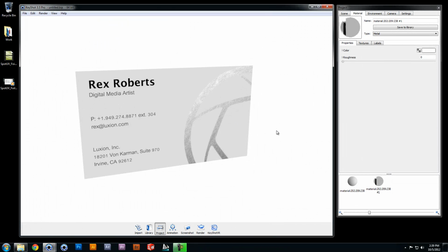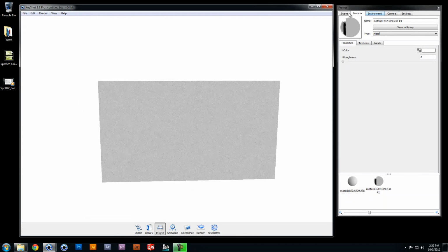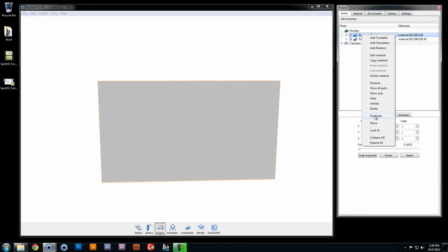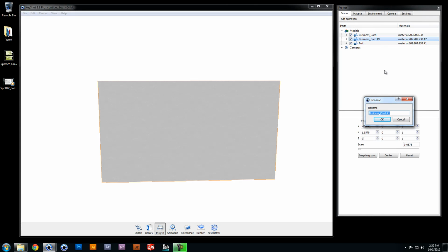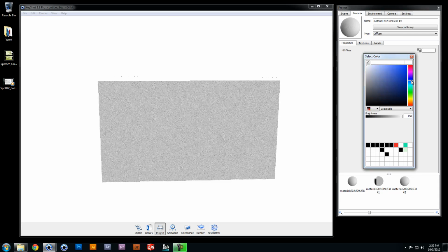So let's go around to the back and follow similar steps to create a spot UV print. We'll duplicate our original model and rename it blue. And we'll also offset this 1/10,000th in the negative direction. And we'll make this a KeyShot blue.